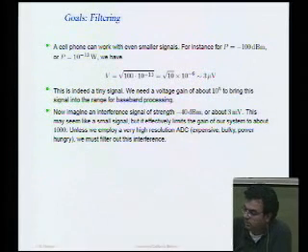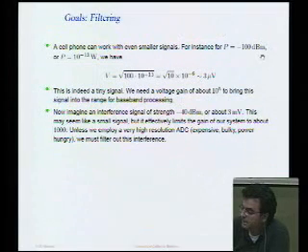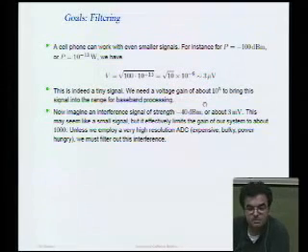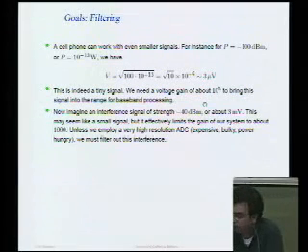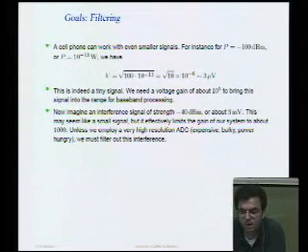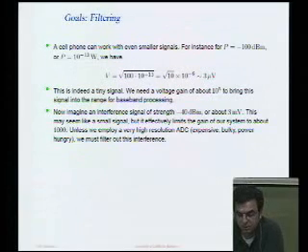Now the other point about communication is that in that near-far situation that we described, while you're receiving this tiny signal, let's say you're also receiving another signal, which is an interference that's minus 40 dBm. Now again, that's only about 3 millivolts. That's a pretty small signal, right? Nothing to worry about, especially when we look at distortion and large signal behavior of transistors. Yeah, 3 millivolts is a pretty reasonably small signal.